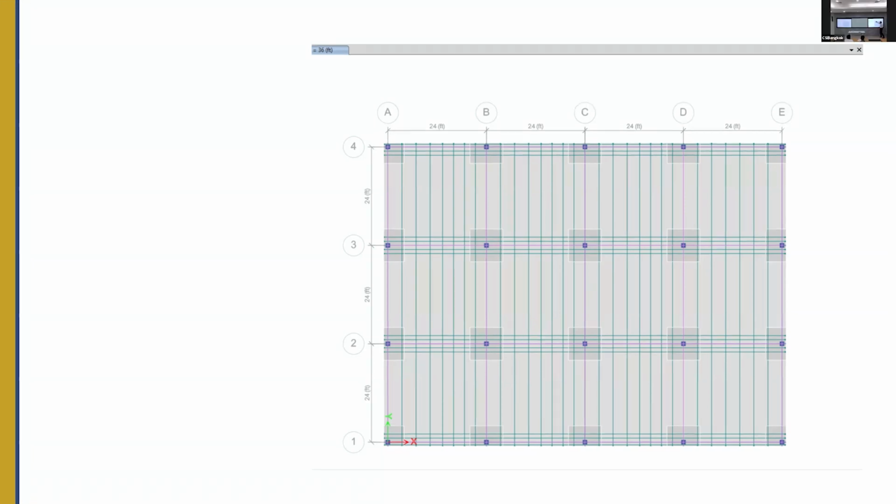So we transfer this load here, and this load is then transferred to the column, same way as before. But now these tendons will help us to reverse the loading cleanly, because each tendon, when you stress it, has a profile, and it will push the slab upwards. So it will balance the dead load.